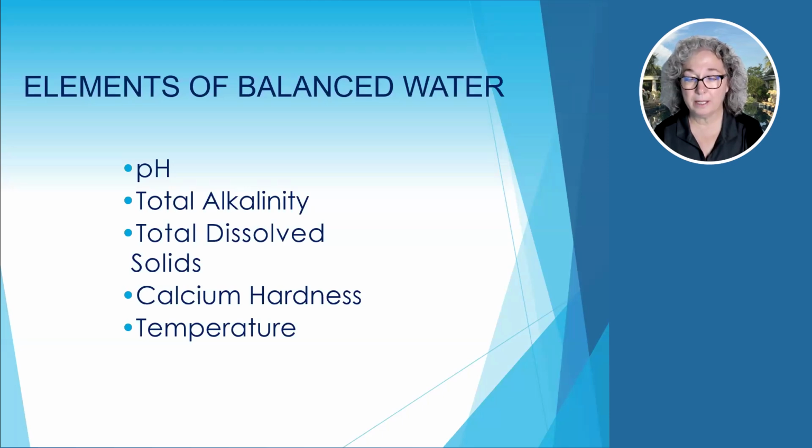Usually when somebody contacts me, and some of you all have, with a pool water problem, the first thing I ask is, what are the water balancing features? Where's the chlorine level? Where's the pH? Where's the alkalinity? Nine times out of 10, we have low alkalinity in the pool water and we get stains. Most of the time we have high pH, also causing some problems in the pool water. So all these balancing factors affect the water and the chemistry.